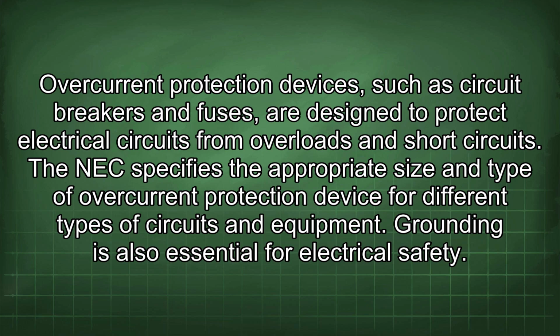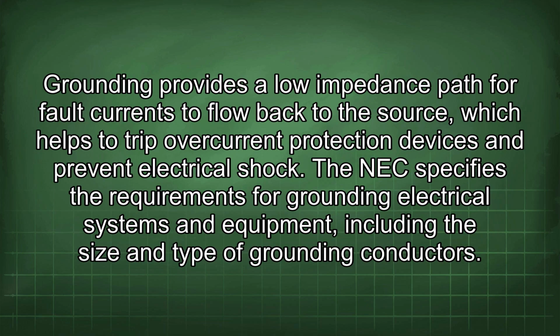Grounding is also essential for electrical safety. Grounding provides a low impedance path for fault currents to flow back to the source, which helps to trip overcurrent protection devices and prevent electrical shock. The NEC specifies the requirements for grounding electrical systems and equipment, including the size and type of grounding conductors.